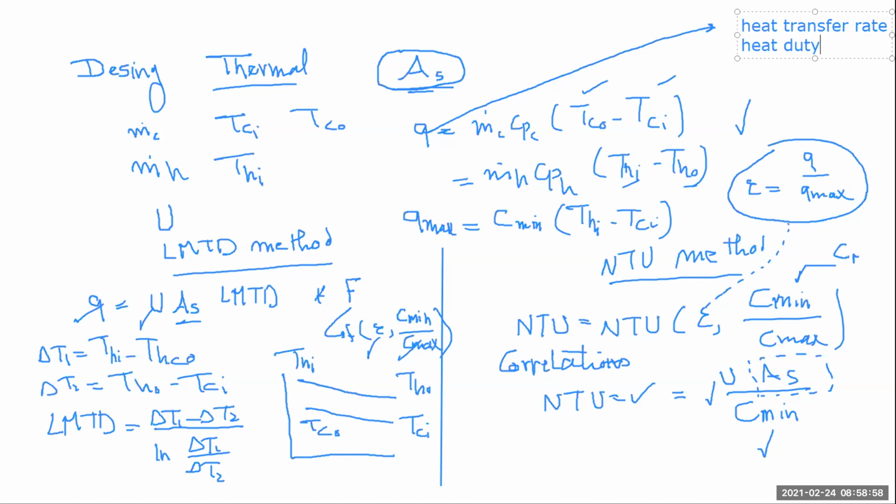This is always going to be needed, except for a specific type of solar collectors, which is called thermosiphon solar collectors. In thermosiphon solar collectors, we have convection and we have motion of the fluid, but the motion is only due to natural convection. Like water, when it's heated, its density decreases a little bit, so it starts to move up and is replaced by cold water down. So you have a natural circulation of water, which is normally slow, and the heat transfer coefficient is lower. But sometimes people tend to use it just to save the use of pumps.